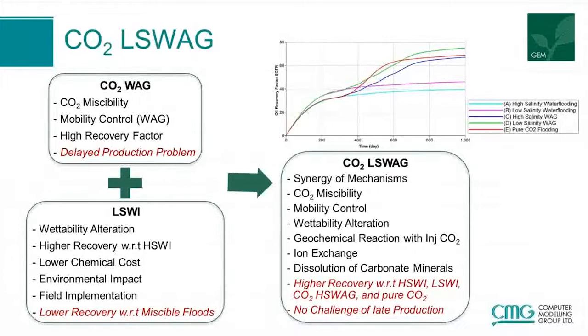In low salinity water injection, we can take advantage of the wettability alteration to have higher recovery compared to conventional water flooding. As I mentioned before, in this process, we have lower chemical cost, less environmental impact, and ease of field implementation. But the issue with low salinity water injection is lower recovery compared to miscible floods.